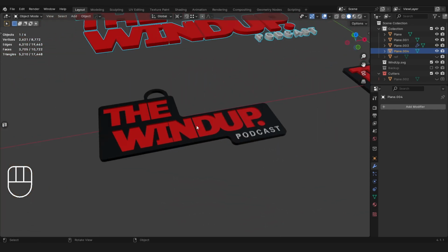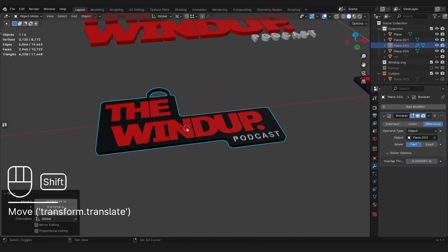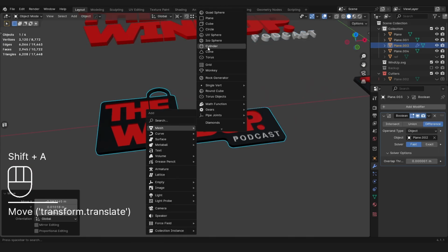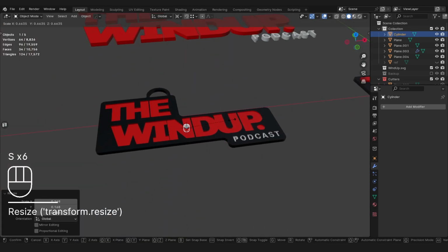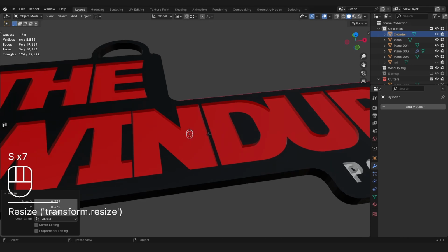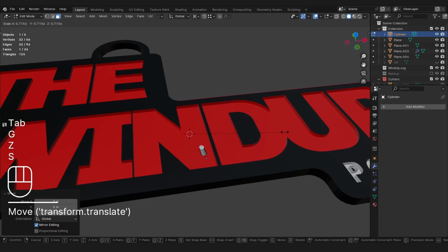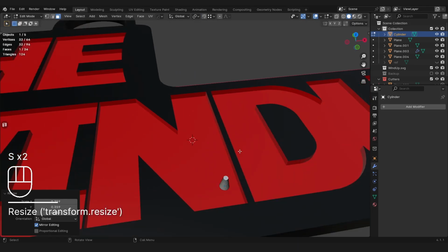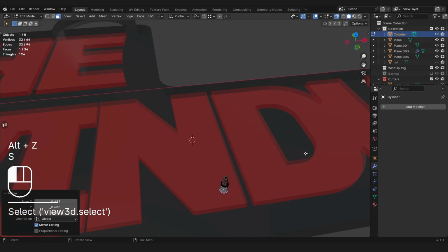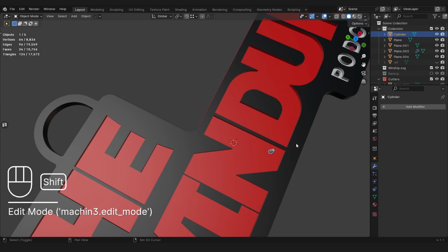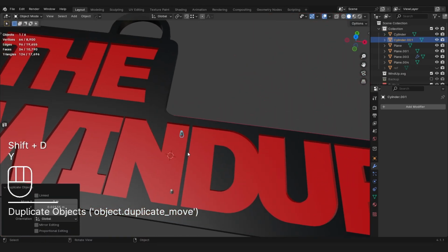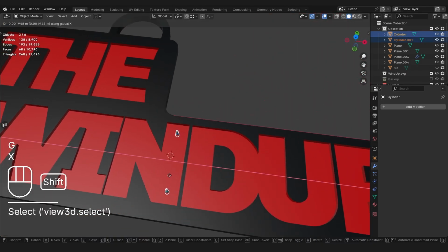Alternatively, another thing that I've done that seems to work really well, let me get my 3D cursor over here, is I can create like a cone or a cylinder over here. Let's scale that down. And I can create little pegs. So that's something that I've done before that seems to work pretty well in certain instances. Obviously, you want to be careful about the proportion of your pegs and how tall they are. Let's switch this back to median point. And also, I like to usually make them a little bit pointy, so that way the top is a little bit smaller. And then I'll put pegs that 3D print on here, and I'll use a Boolean to sort of make this something like that.